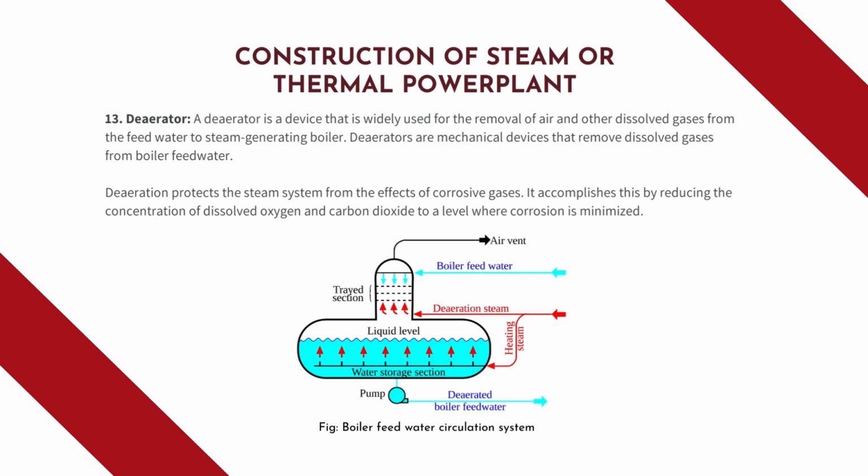So, with the presence of oxygen or any other gases, there may be the possibility of corrosion in the boiler section. To remove or minimize this problem, we locate the deaerator in the system.